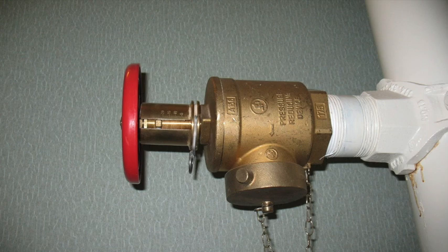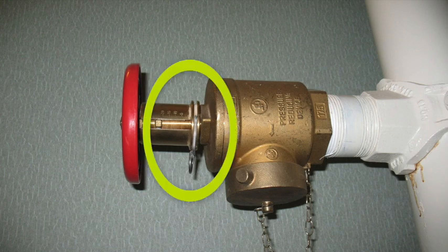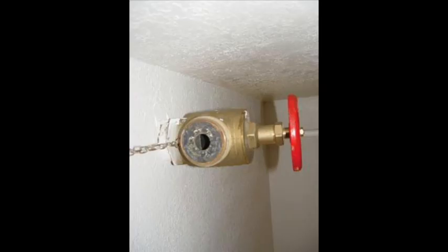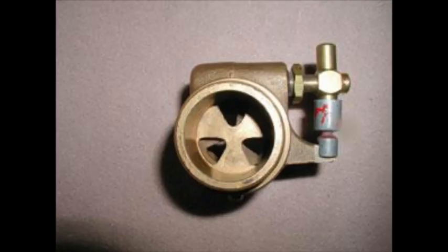This hose valve is equipped with a similar device, but is equipped with a limiting pin. Simply remove this pin to adjust the device as needed. Some hose valves are equipped with orifice restrictors. These devices obstruct the outlet connection to reduce flow. These devices are generally easily removed with a small screwdriver, a spanner wrench, or even channel locks.